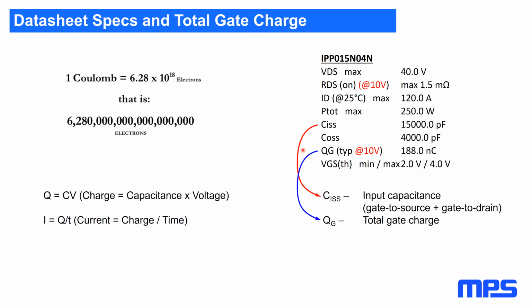You need to do that because if you just use one MOSFET, when it's turned off, the body diode can conduct current the wrong direction. Quite often you'll see them configured that way. And MOSFETs don't care which direction the current flows once they're turned on. So even though one of the MOSFETs in series appears to be backwards, really it's acting like a diode, essentially.